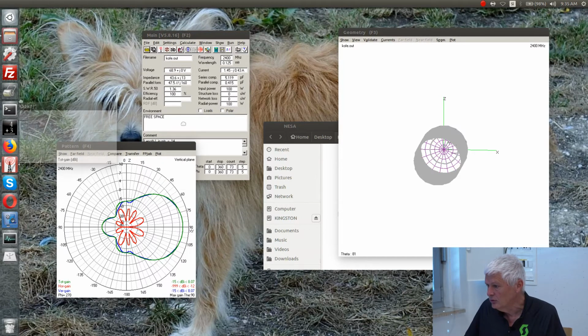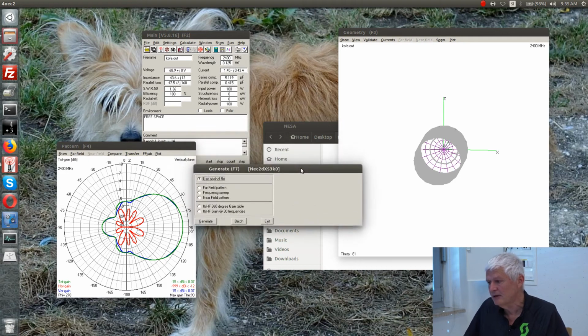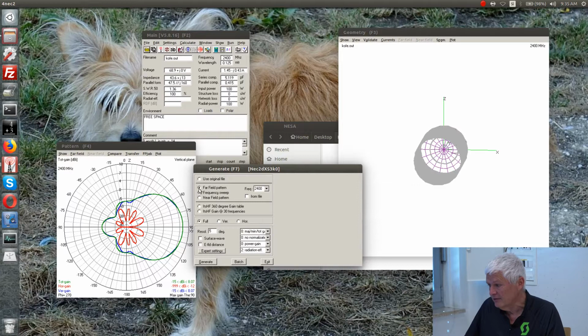We are going to specify something somewhat different from our original file request. We are going to say the far field pattern, and we are going to calculate the radiation efficiency. Where is the radiation efficiency? We only have lossless materials. We have perfect metals here. There is no loss in the metal. But NEC2 is calculating powers in two different ways.